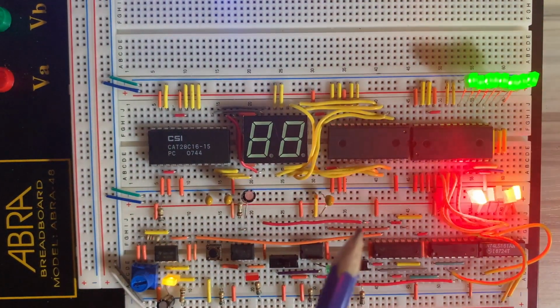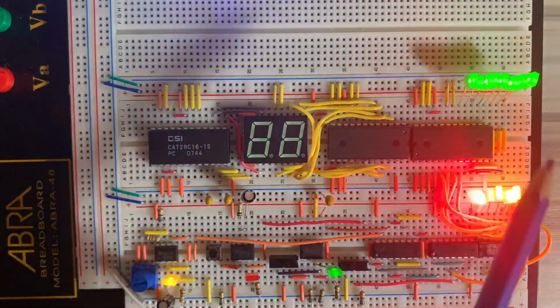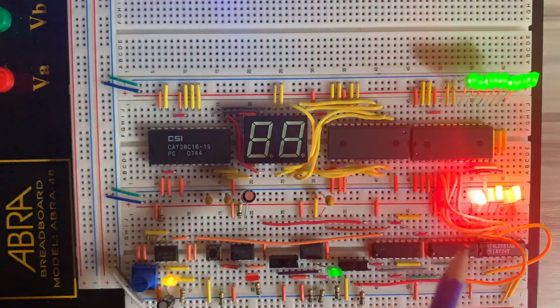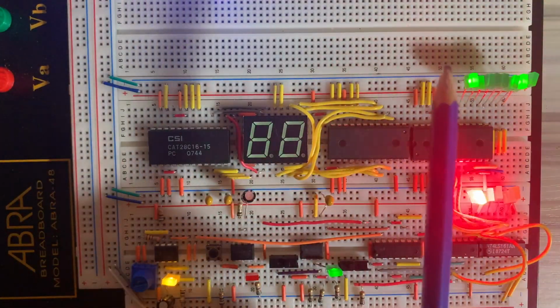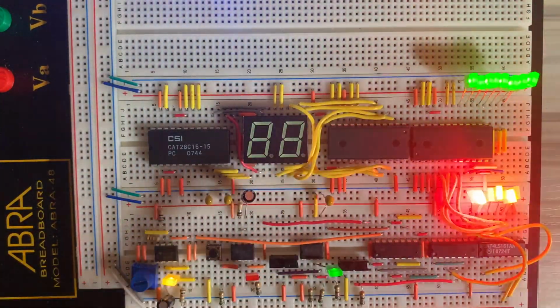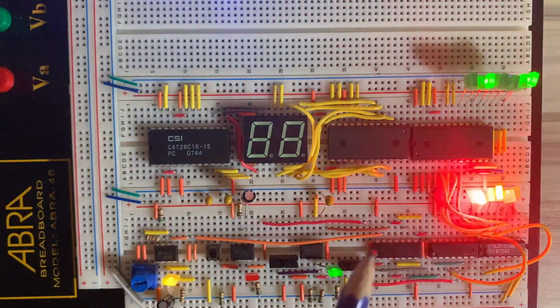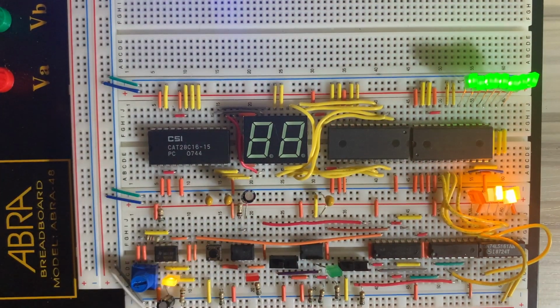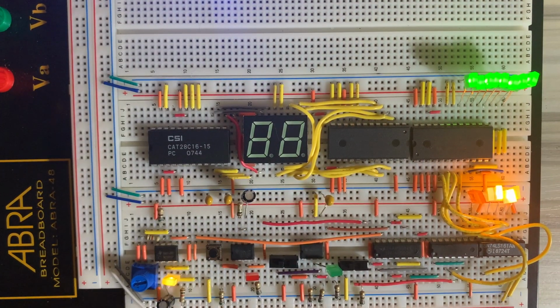This is the second part of CHUMP, which uses an EEPROM to program the code onto CHUMP after each subsequent clock pulse on the program counter, and the output is represented by these 8 LEDs, representing the output of the code. It is currently displaying Dave Feinberg's code.